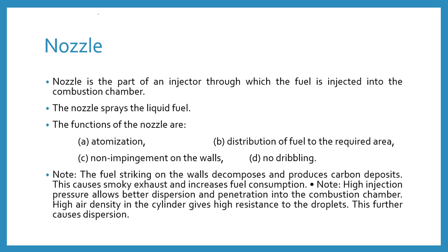The functions of the nozzle are: one, atomization; two, distribution of fuel to the required area; three, non-impingement on the wall; and four, no dribbling. These are the main four functions of a nozzle fitted inside the fuel injector.